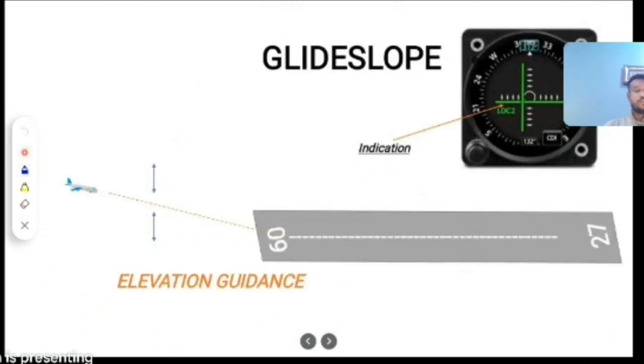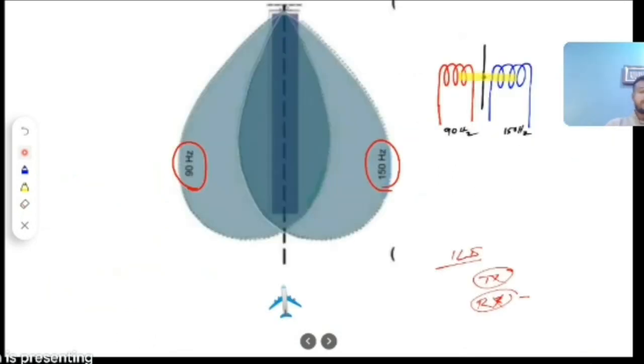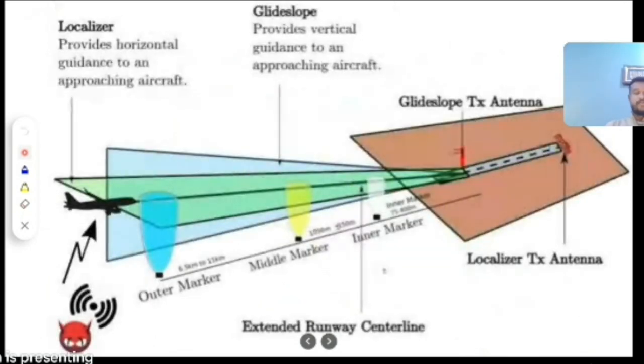So this is the needle which is indicating. There are two needles, one indicating the localizer, another the glide slope. As I told you, now we will sum up the whole function. These are the electromagnetic waves, green. Sir, marker beacon is oral only? Absolutely. Marker beacon gives only an oral advisory, an oral indication you can say. Plus there will be an indication in the PFD, written as marker MM, OM, IM. That's it. No distance will come. It is a discrete distance you have to understand on your own.